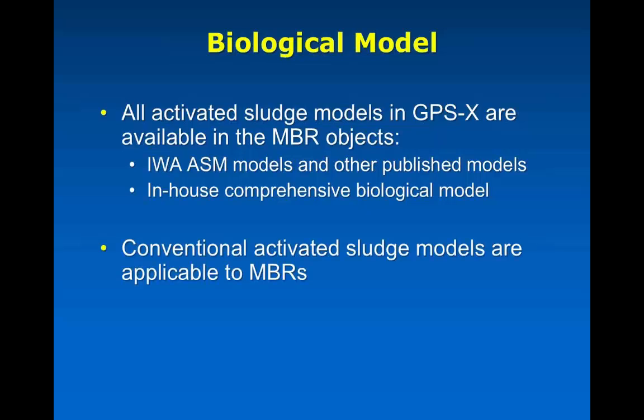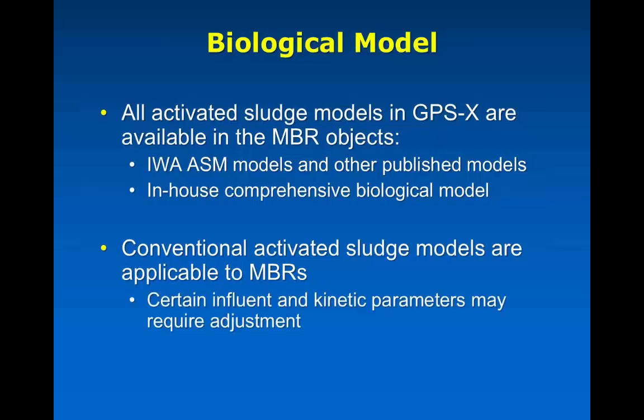Now, conventional activated sludge models are actually applicable to MBRs. There's a fair bit of research in the literature that says the structure of the model itself is totally valid in an MBR context. However, you may find that there are certain influent or kinetic parameters that require adjustment. I've put a note on here that you can see a couple of papers that are referred to, and if you'd like me to send you these references, just send me an email after the webinar.